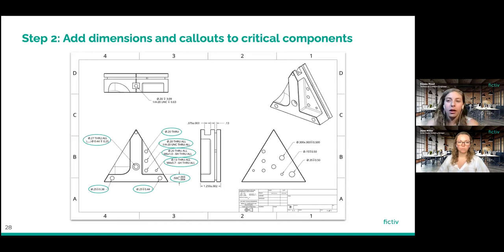Conversely, with our inch tap, so 1/4-20, the 20 aspect means that there are 20 threads per inch. And so those are some good different things to know about taps, whether you're tapping in imperial units or in metric units.